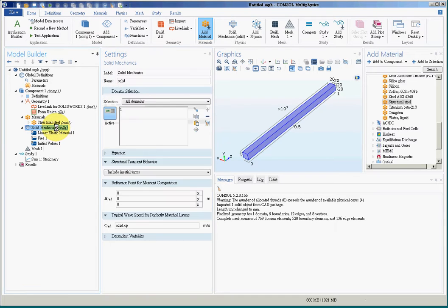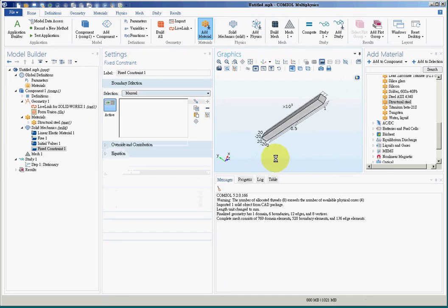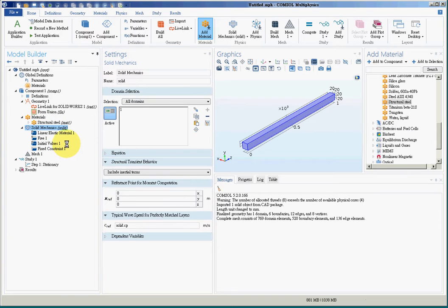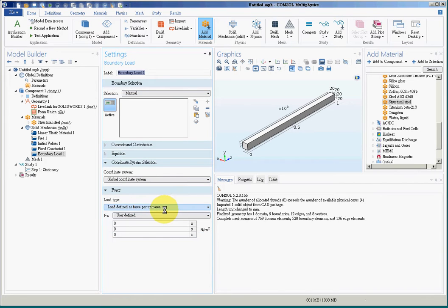Step 4, boundary conditions. And there's no confirmation step, so you got to be very careful about this. Loading, type of load, concentrated force, area, surface of load, direction of load, y direction, magnitude of the load, 100 Newton in negative direction. So we're finished with the definition of the beam,